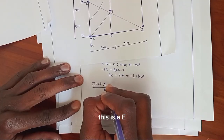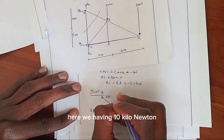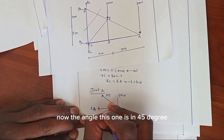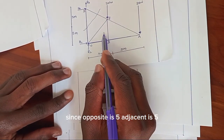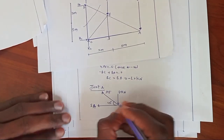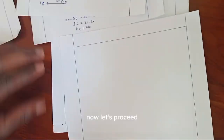This is AE. Here we have 10 kilonewton. Now the angle of this one is 45 degrees. Since opposite is 5, adjacent is 5, tan inverse of 1 is equal to 45 degrees. Now let's proceed.